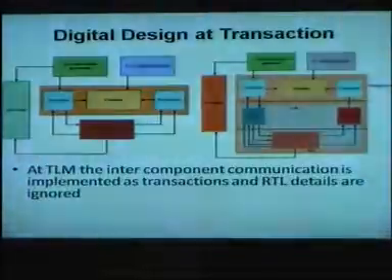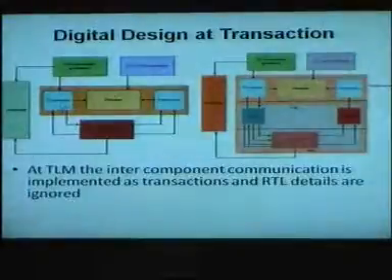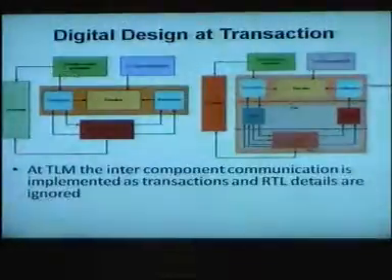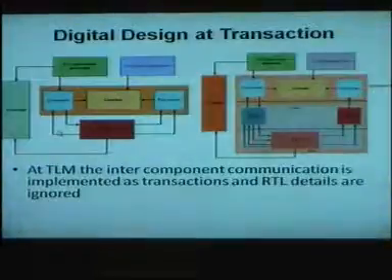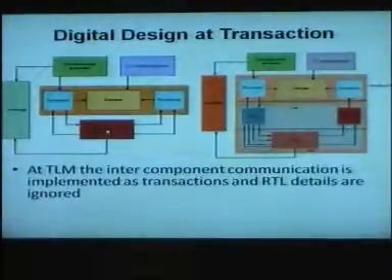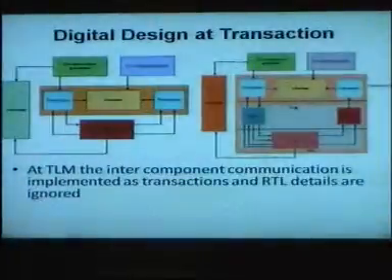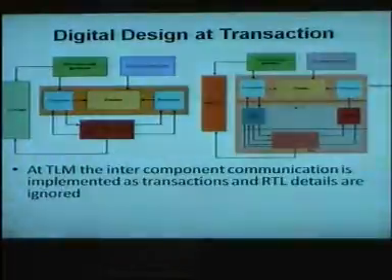Okay. So as you see, this is a transaction level model, where this is a transactor, and the transactor primarily runs C. You generate your test vectors, and you load them into your device at the transaction level. You're making a transaction, not worrying about the RTL level detail of how this data actually goes from one device to another.